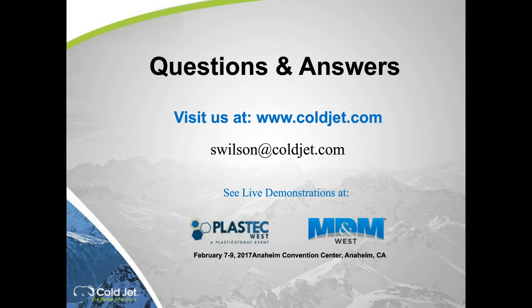All right. Let's see. Albert asks, has wear been observed on molds that have special coatings, such as chromed or whatnot? We clean all kinds of coated molds. Matter of fact, I've got a third-party relationship with Oerlikon Metco. Sulzer puts DLCs, diamond-like coatings, on molds. If you were to look at their 80-page presentation, about three quarters of the way through, there's a picture of a Cold Jet machine. We'll just say that they recommend dry ice to clean their coatings.